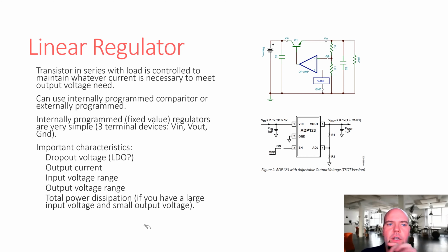And okay, let's talk a little bit more. We showed it just now with BJTs. It's more commonly modeled as an op amp. An op amp is going to get better performance there. An op amp again is pretty much just a collection of BJTs that are cascaded to get higher gain. And the higher gain you get, the smaller error you're going to get in your output with a linear regulator. And there's a couple things to talk about with this, though.